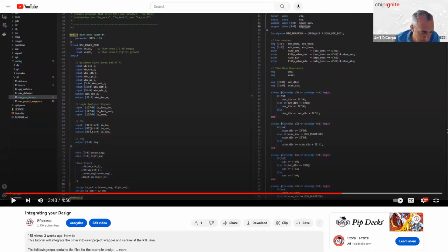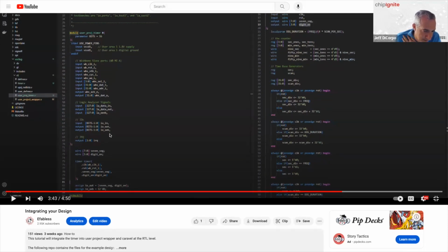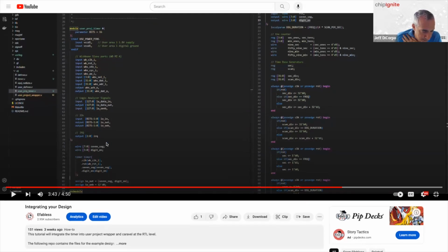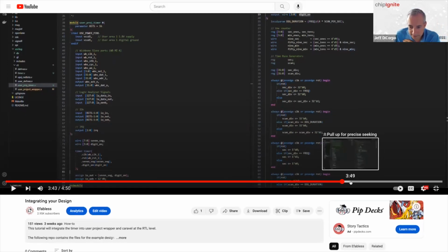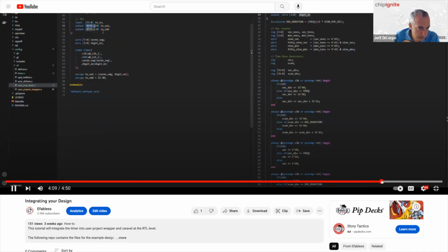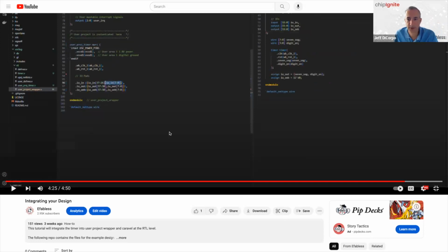There's a total of 38 pads, 0 through 37. There are vectors for each of these signals that map to each of the various IO pads. And then there are IRQ signals here. Again, you can find more documentation on that if you're interested in using that functionality. Okay, so I think those are the key pieces for integration. IO in will be left unconnected, and we use 12 GPIOs. I think that's probably sufficient on that one.